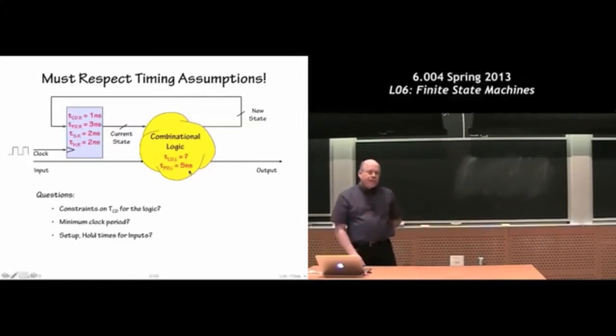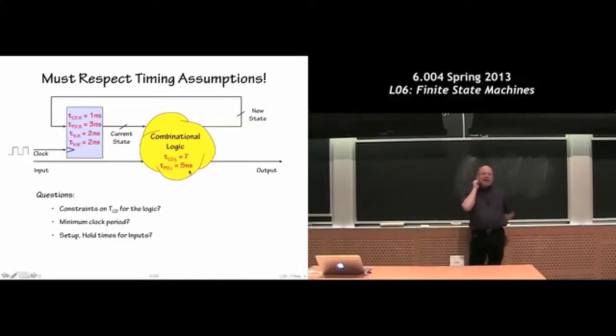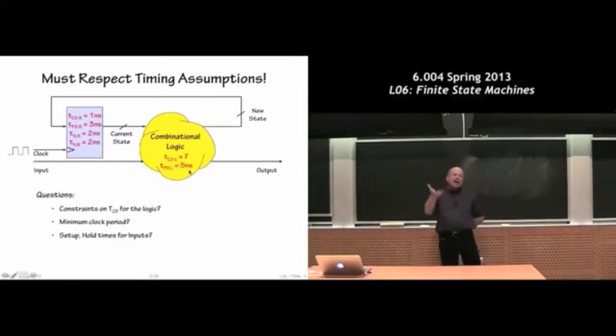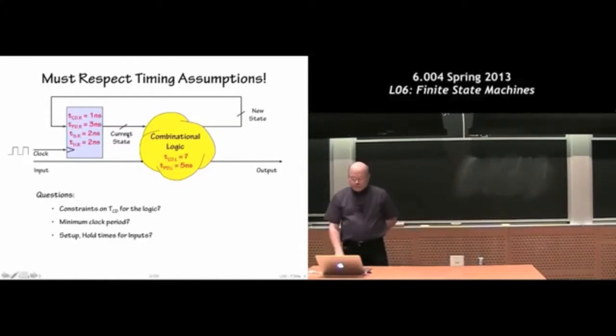Yes? One register just keeps track of 1 bit, right? So if you want k bits, you need k of those individual 1-bit registers. We often draw them as a single box and just somehow indicate that there's k bits coming in and k bits going out. And you should just know that that's k copies of the single D register that we've been talking about. So we can have a sort of sloppy notation, but it tends not to be ambiguous. You just have to look at the number of bits that are being stored there. And you say, oh, I need as many individual register bits as the bits I'm trying to remember.